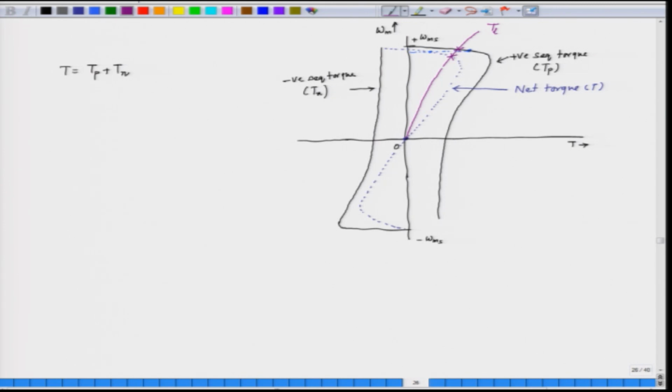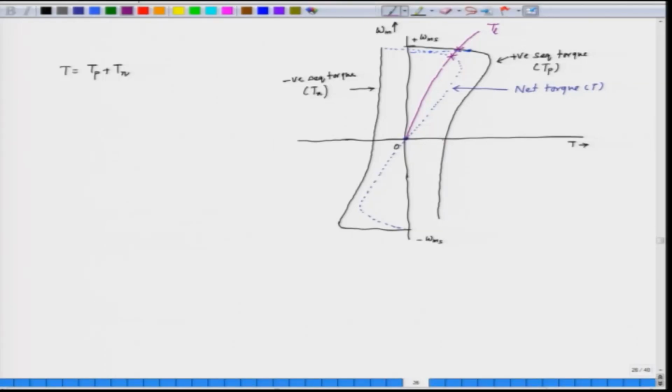So, the motor continues to rotate. When we single phase an induction machine, it continues to rotate, but the speed will be a little bit reduced. The speed will be close to synchronous speed, but it is reduced from the earlier value. Here we are assuming that the rotor resistance is low. So, the speed is reduced, but the motor continues to rotate with a reduced power, because the torque is reduced, and the speed is also reduced.